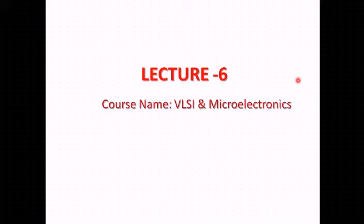Next, we have studied the small geometry effects and also the short channel effects. As we know, the small geometry effects are of two types, such as the short channel effects and the narrow channel effects. So we have started with the short channel effects and we have studied the channel length modulation, threshold voltage lowering, punch through, sub-threshold conduction and the velocity saturation. So today we will be starting the narrow channel effects with a brief continuation of the short channel effects. So let us start lecture number 6.